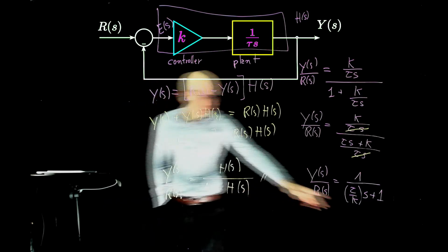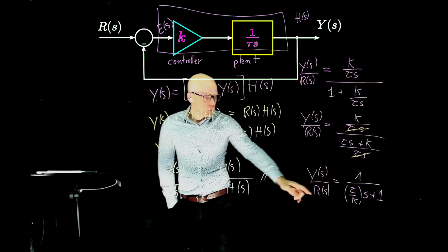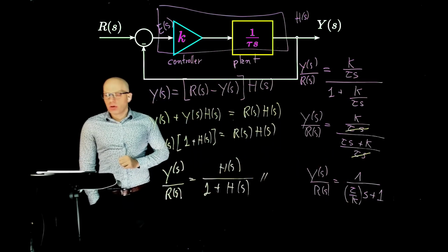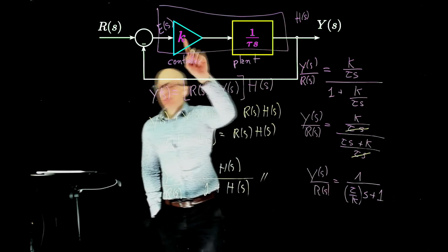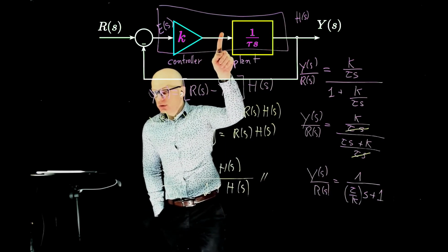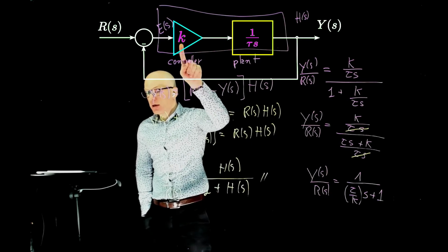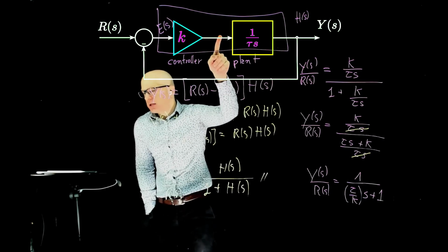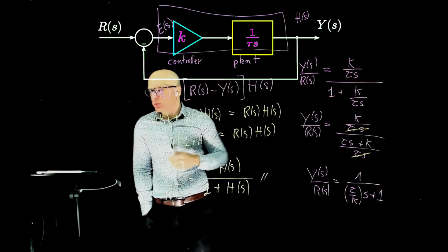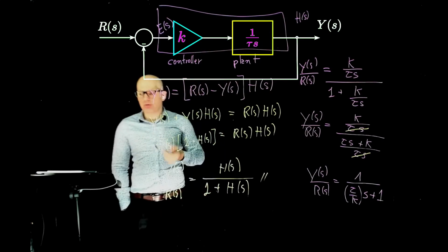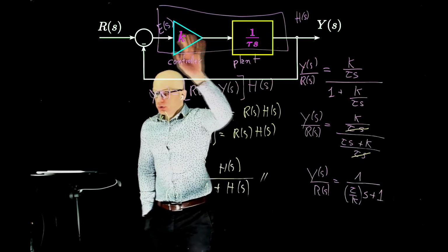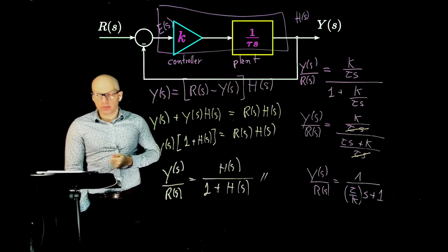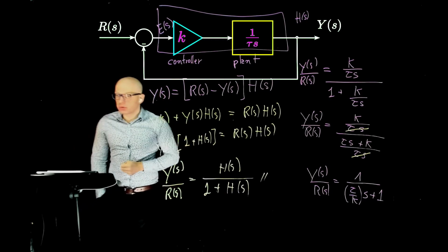Theoretically, there is no limit. We could make K tend to infinity, and the system wouldn't even have a transient, it would just reach steady state right away because the time constant would be so small. But remember that K is a gain that we need to establish here. So if this is a voltage, there is a physical limit for K, because we don't want a small error here to generate, let's say, 1 million volts. We can't do that. We need this output to be reasonable, within, let's say, 48 to 100 volts maximum. So we need to tune K to also respect the limitations of the hardware we are working with, even though in theory there is no limit for it.